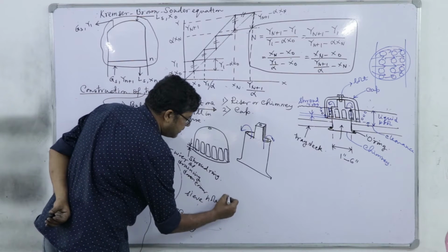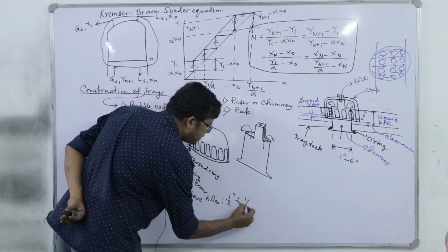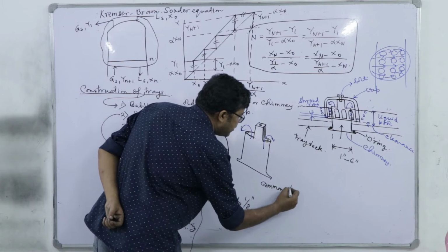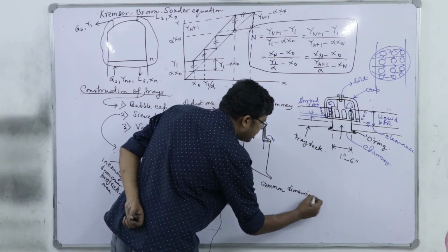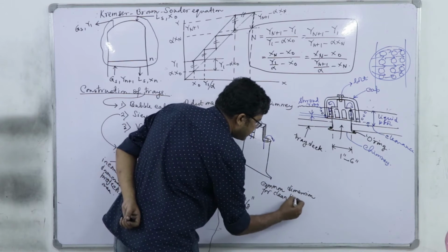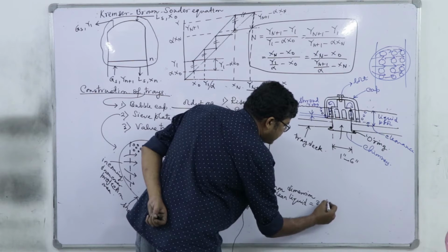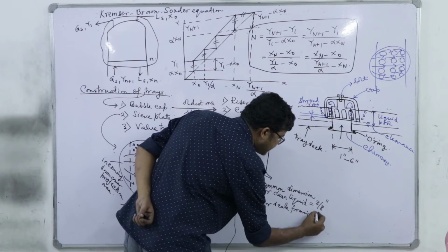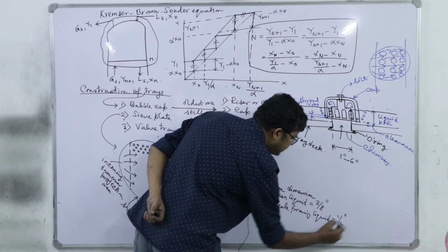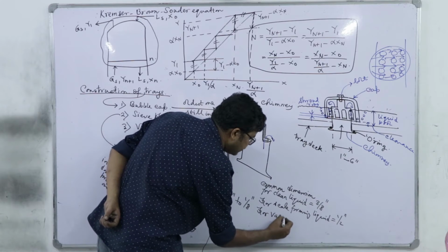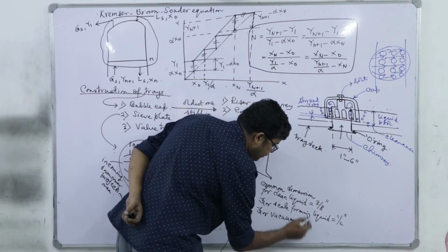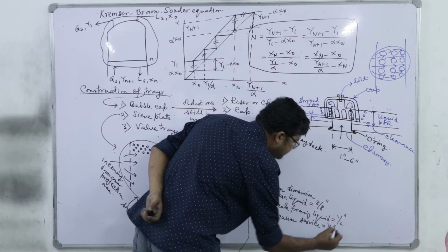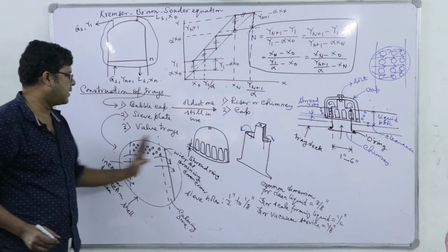their dimensions is half inch to 1/8 inch, right, and common dimension for clean liquid is 3/8 inch. For scale forming liquid, we may go up to half inch. For vacuum service, where the weeping is highly probable, we have to reduce this opening. It is 1/8 inch, right. So, it moves from one end to another end.